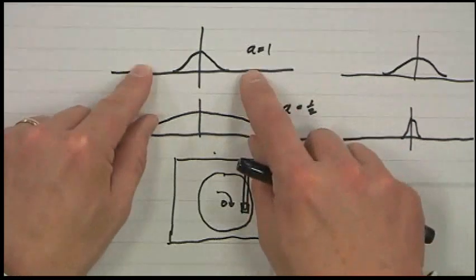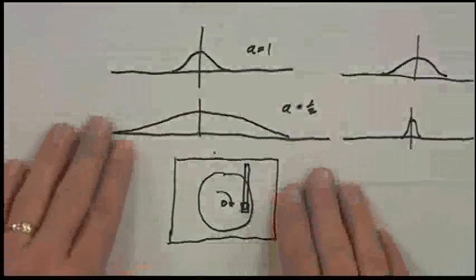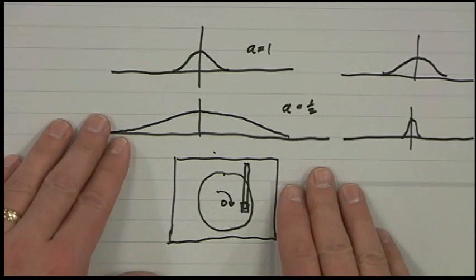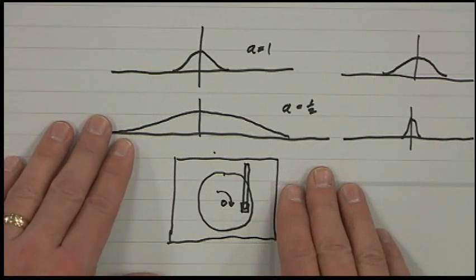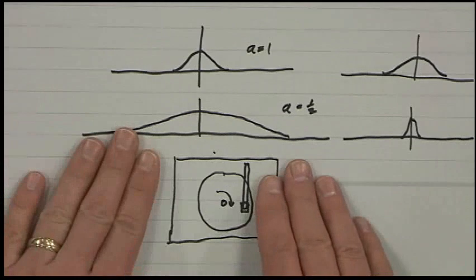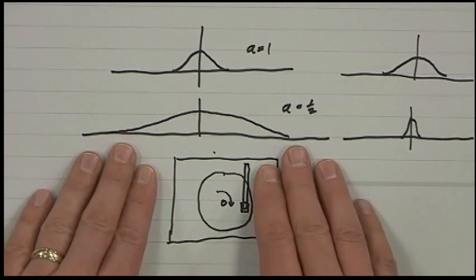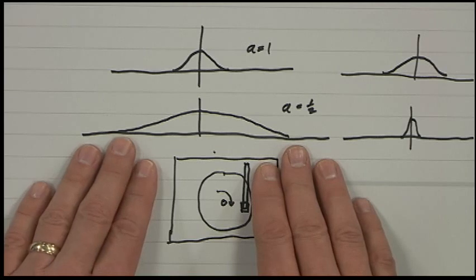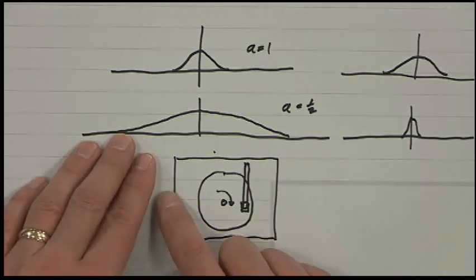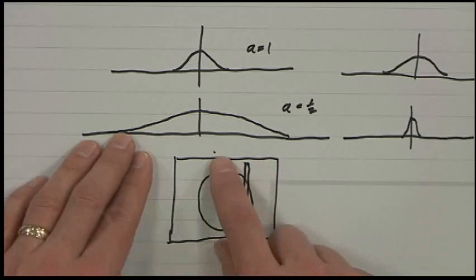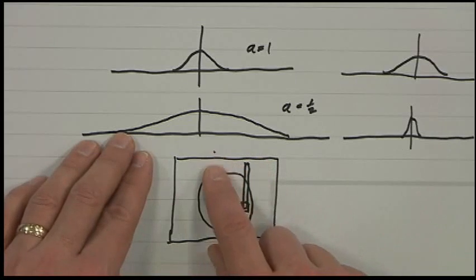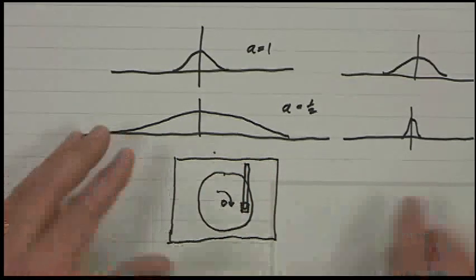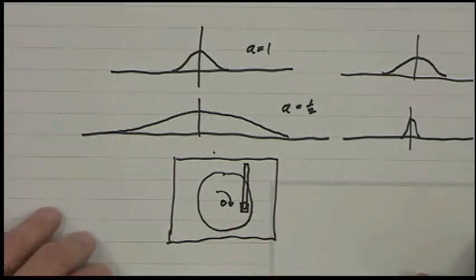So the scaling property works beautifully in continuous time, but it doesn't work in discrete time. And it's actually a wonderful thing that it doesn't work, because the fact that it doesn't work in discrete time has employed thousands and thousands of engineers for decades, trying to solve this problem. There's multi-rate filtering, and there's wavelets, and all kinds of fancy mathematical techniques have been used to address this fundamental problem: what do you do when you have to resample a discrete time signal?